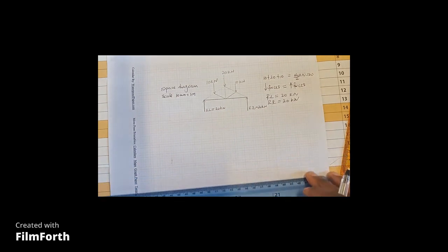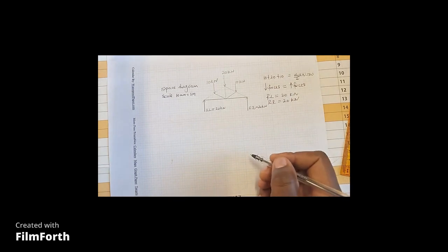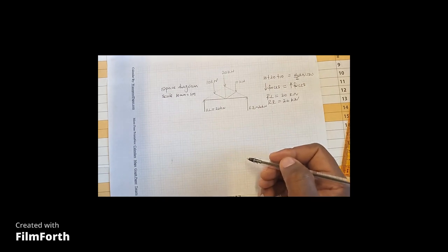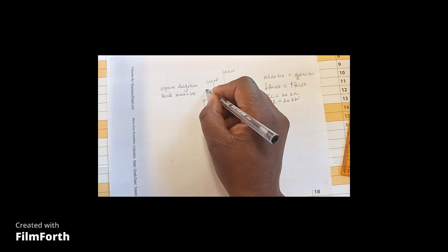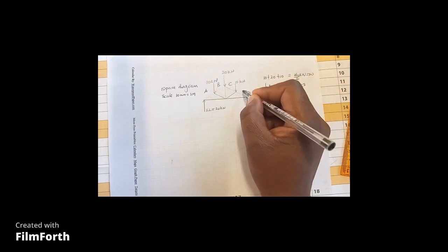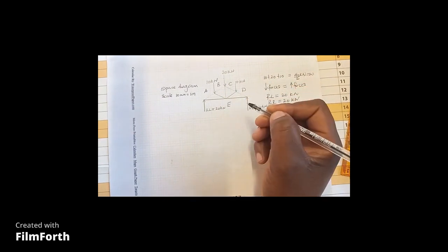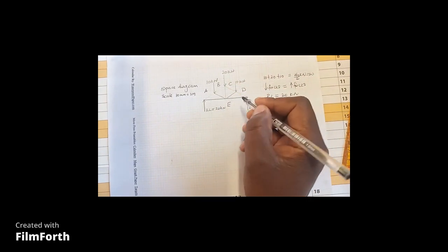It is now time for us to come to the single line diagram, which is going to combine the triangle of forces together with the polygon of forces into the single line diagram. But before you do that, you need to apply Bow's notation to your frame. So for Bow's notation, you can simply start from the left-hand side, put your A, your B, C, D, and underneath it's E. When we go inside, we continue the lettering.